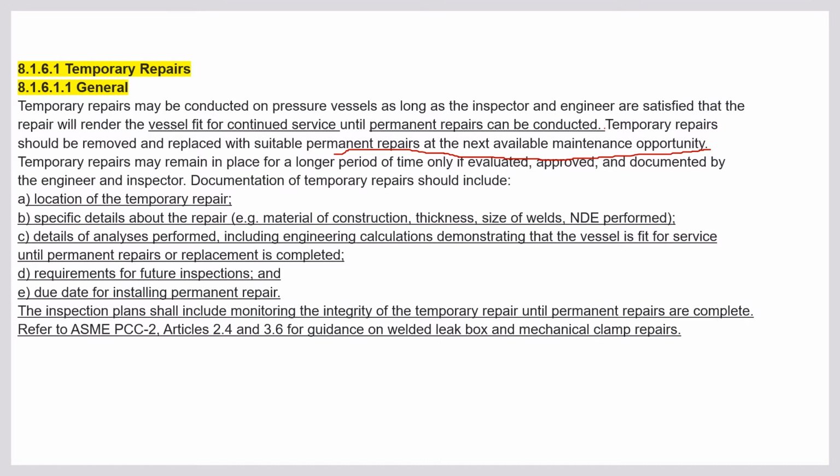But after a certain time, we have to replace the temporary repair and do permanent repair. Okay. So temporary repair may remain in place for a longer period of time only if evaluated, approved and documented by the engineer and inspector, not either one, both have to evaluate. Engineer has to evaluate and inspector has to evaluate.